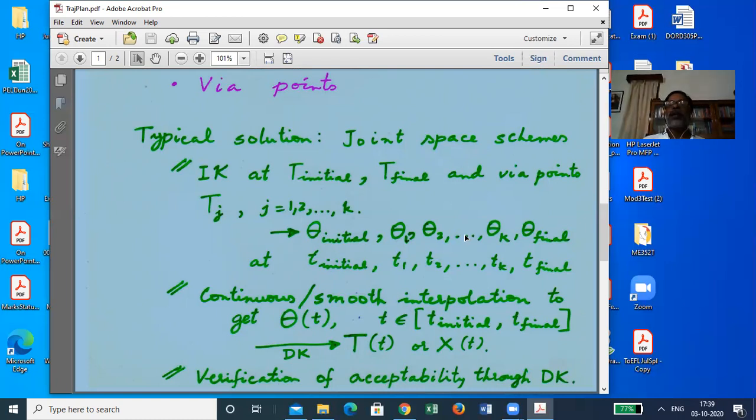So for the planning of each of them, as long as they satisfy the correct time, correct position of their own joint value, we don't care for the others. And that is how the complete coupled problem actually gets decoupled into 6 parallel strands of similar problems.